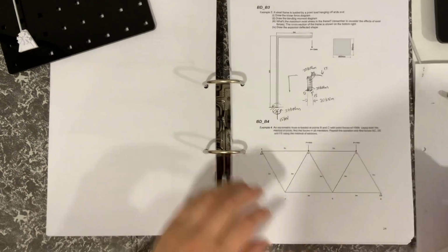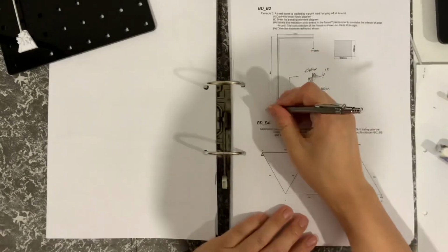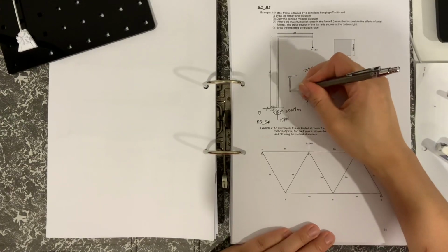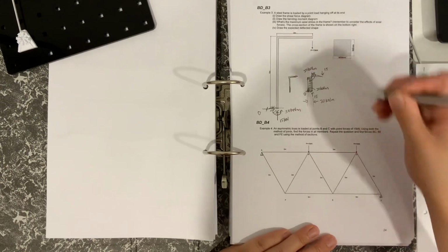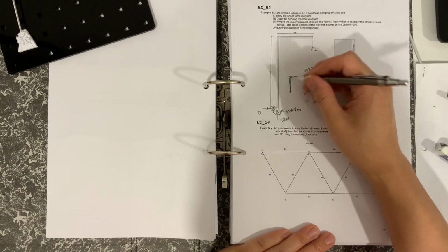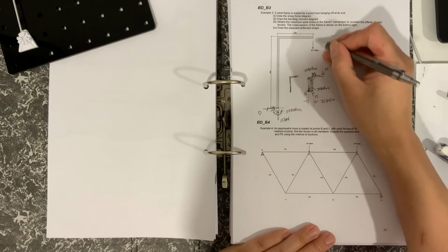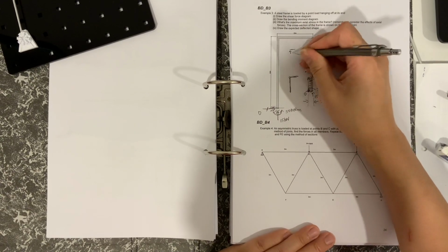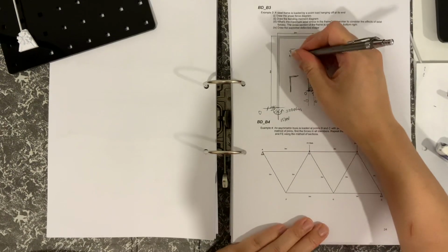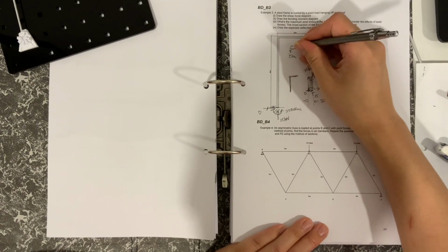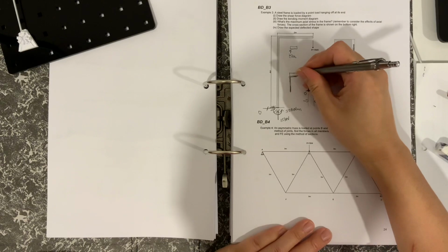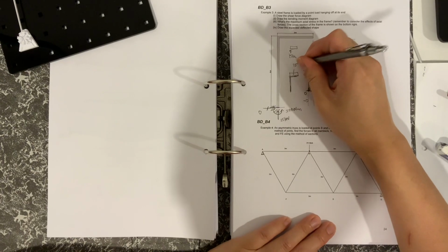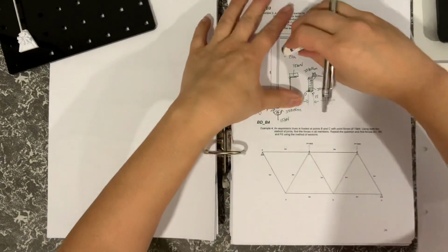30 kilonewton meters for the reaction, and the horizontal reaction, of course, is going to be 0. So when we draw the shear force diagram, I'll draw a double line there, and the shear force is going to be 0 there. Up here, moving from left to right, you could transplant that 15 kilonewtons up to the top so that it's in equilibrium. 15 kilonewtons, and so the shear force diagram will look like that, which I'll draw there and show as 15 kilonewtons.